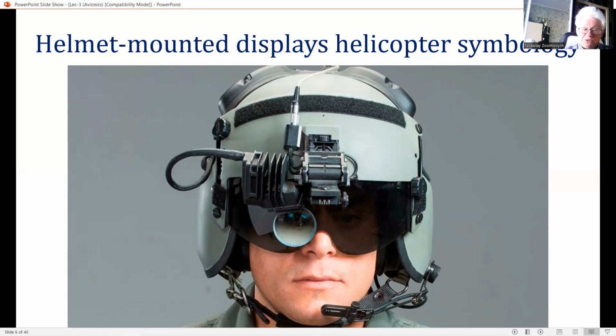by displaying the TV picture from a gimbaled infrared sensor unit, which is slaved to follow the pilot's line of sight. The pilot's line of sight, LOS, with respect to the airframe, is measured by the head position sensing system. Such a helmet can also incorporate image intensification devices with a video output to provide a complementary viewing system.